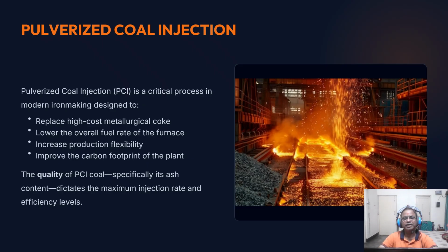So by optimizing PCI, we are not just saving money, we are significantly lowering the carbon footprint of our entire plant also. And in this context, the role of pulverized coal injection is going to be immense for any blast furnace operator. So each one of us try to run the furnaces with a higher coal injection, provided with the compatible replacement ratio that need to be evaluated all the time. Otherwise, it is a wastage.